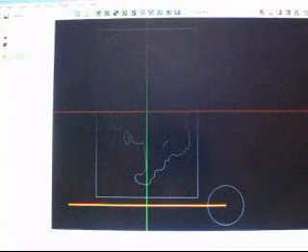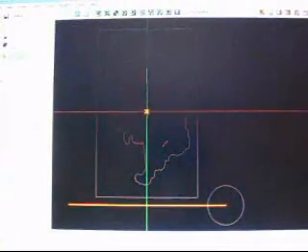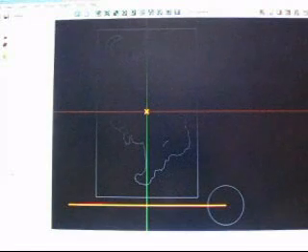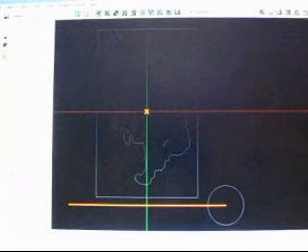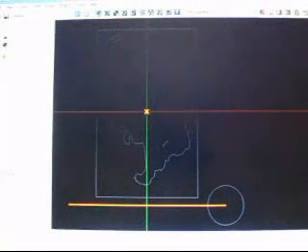So when I generate the tool path, let's just go through the parameters of the tool path itself. First, obviously, you have to enter a tool diameter for this because it uses a step over and offsets for the tool. So our step over is going to be 40% of the tool, 0.4 in this case. That's what you call it. 0.4 is 40%, okay?